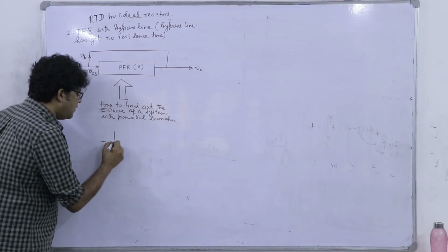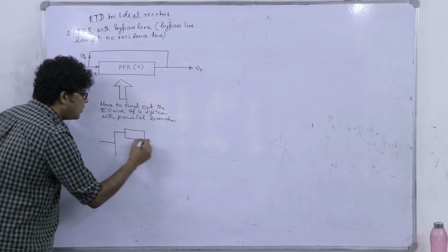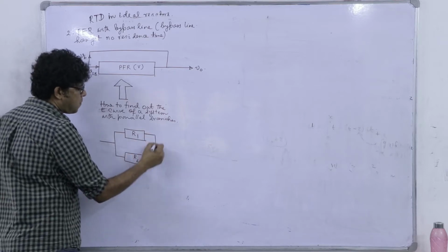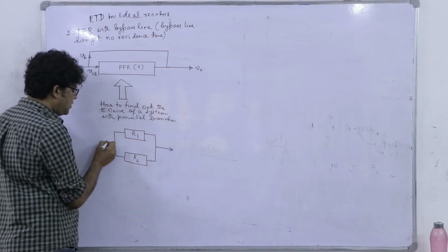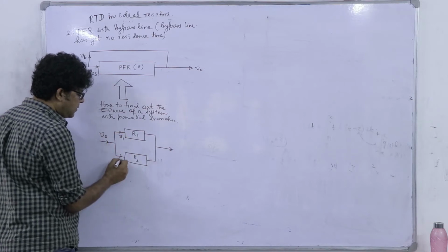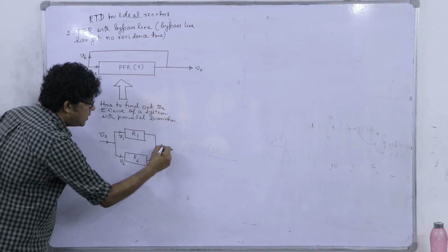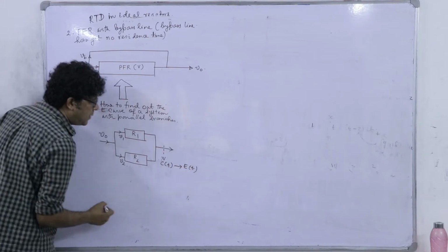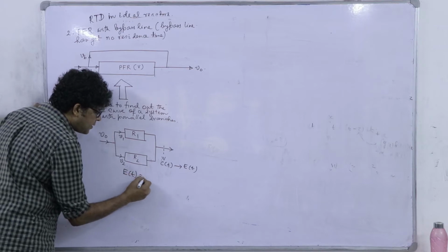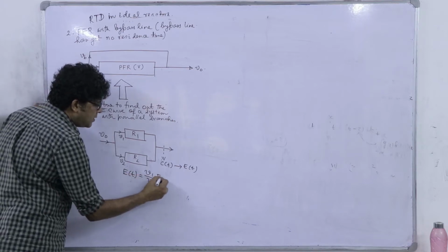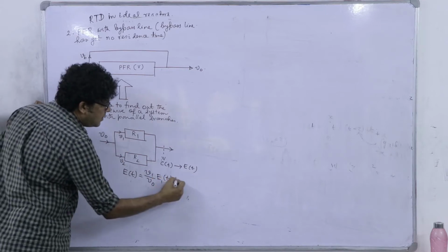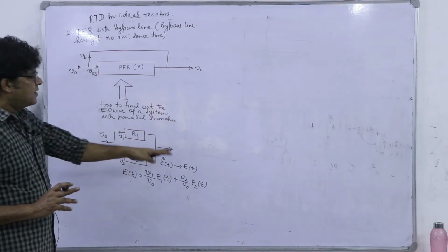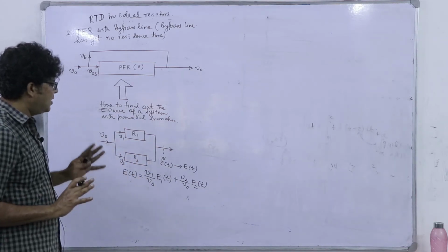See, I have two reactors. This is R1, this is R2, right? Delivering the product. Here we have V naught, this is V1, this is V2, right? So, overall E, what we are getting from here, from C curve to E curve, what we are supposed to get for a pulse. So, E curve is equal to V1 by V naught times the E curve of individual reactor R1, plus V2 by V naught, that of E2. Right. This I am not proving, it is quite understandable and simple.